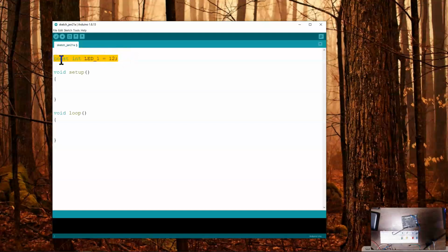I have to actually tell the Arduino board that I'm going to be using pin 12, especially for doing output. So the 12 really is just me putting a constant number. This does not say that this is connected to that pin yet. It's not until we start using the functions and tell the function, hey, give it the number 12, that we're working with that pin. So first step, you have pinMode, explained in the simulator video, LED_1, setting it for output. Boom.